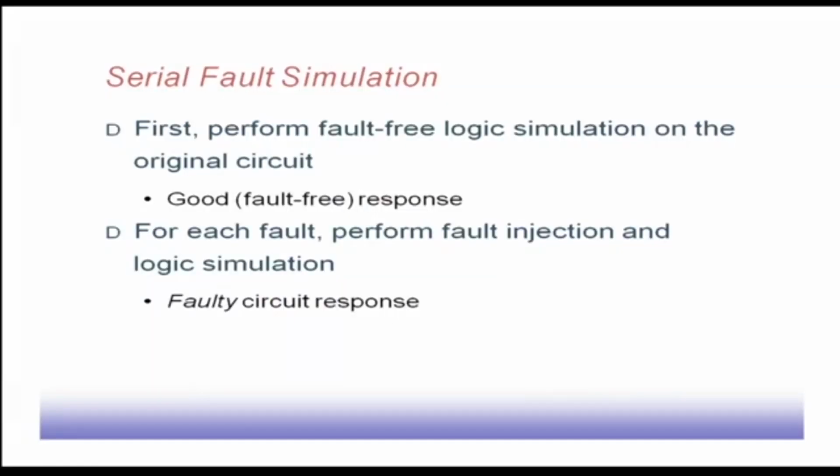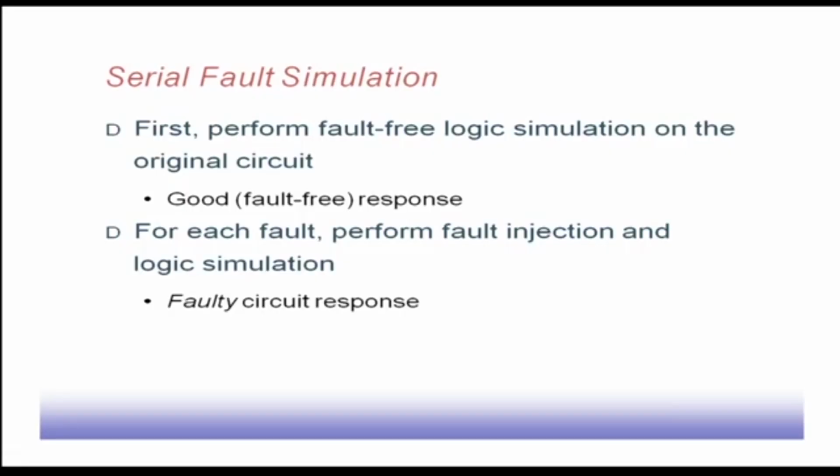Then for every fault, we perform fault injection and logic simulation. Performing fault injection means we modify the circuit description as if that particular fault has been inserted into the circuit, and then we again simulate the circuit. So, in the presence of that particular fault, what is going to happen? That is the logic simulation after doing the fault injection.